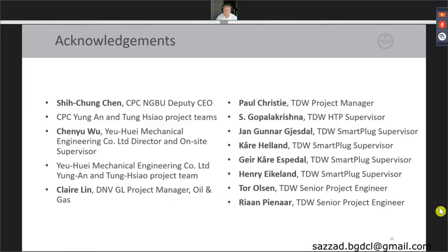Okay, thank you, Rolf. Mr. Vignesh PV asked another question: what is the operating pressure of the pipeline, and during the hot tapping, how was pressure maintained? In this particular case, the shut-in pressure, which is the pressure when it stops the flow in the pipeline, was 58 bar. So that was the pressure that we had, and when we did the hot tapping operation, the pig trap was also pressurized to 58 bar. So that was a stable pressure along the entire 238 kilometer pipeline, which kept the pressure stable.